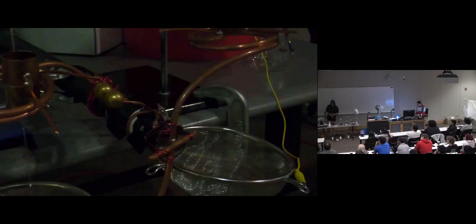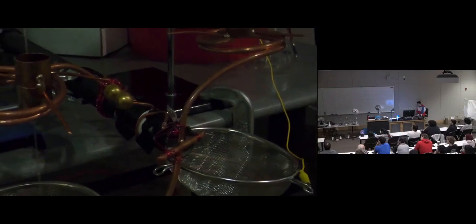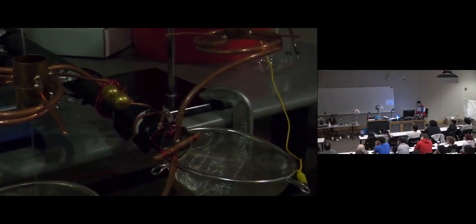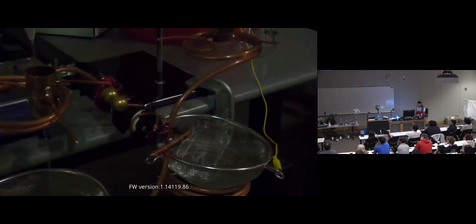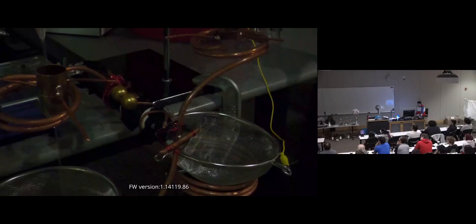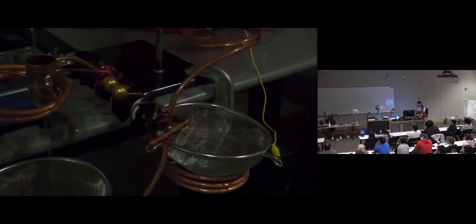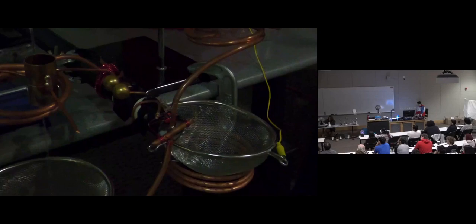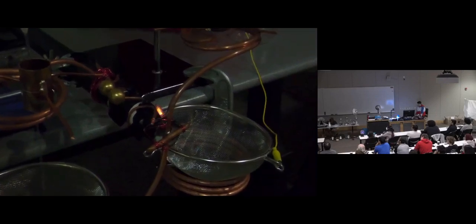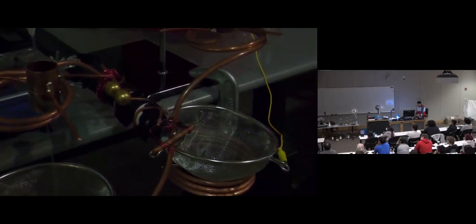You leave it on there, I'll explain why it's happening. So what we've done, you zoom out a little bit. You see the two little steel balls? We put the steel balls far enough away that we have to build up a few thousand volts for a spark to go across. And when the spark goes, that light turns on. So we are generating several thousand volts on each side just by letting gravity separate our induced charge from positive and negative. This is the Kelvin water dropper experiment.